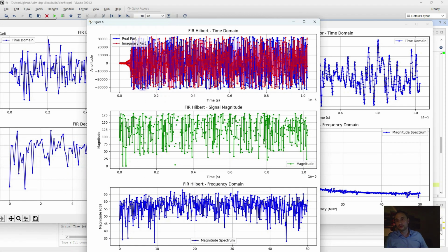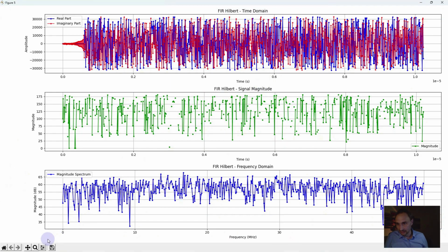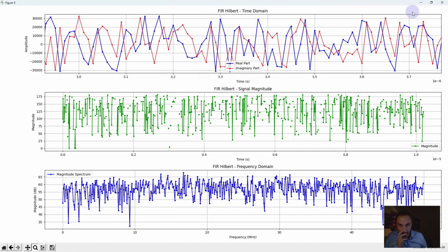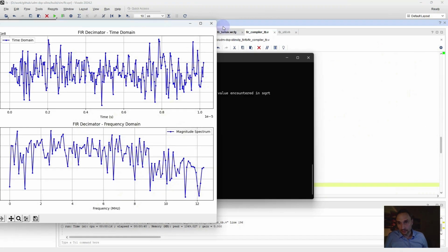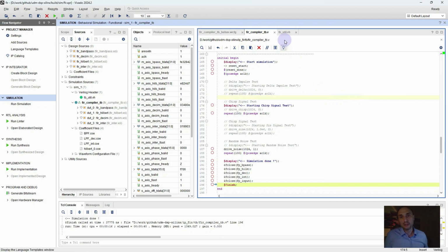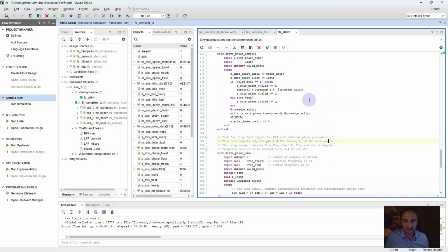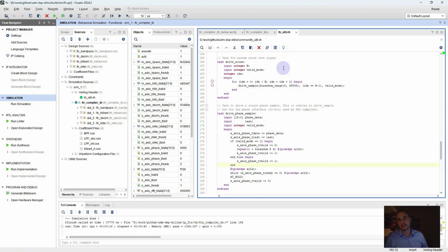So the Hilbert transform is here, where all harmonics are shifted by 90 degrees in phase. Therefore, any test case can basically be set by using this Verilog header. The test signal can be used not only as a test case for DSP analysis, but also to verify your AXI stream interface for your embedded infrastructure, for your embedded environment.